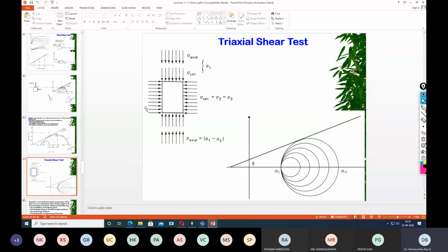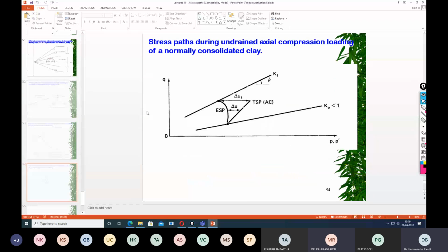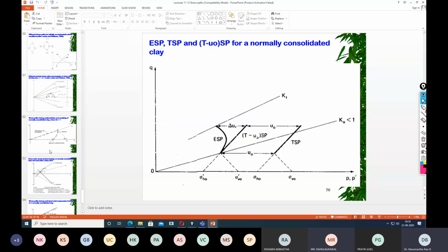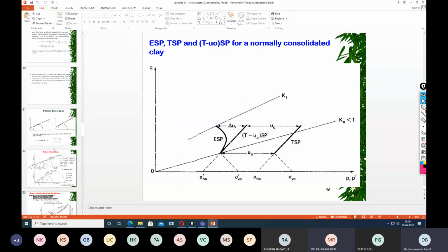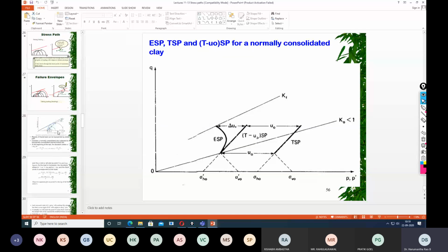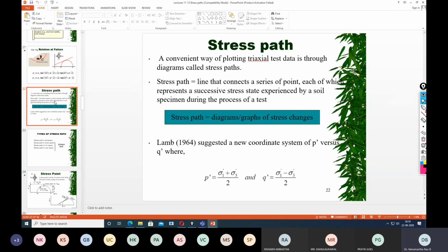Why do you think it should fail immediately? Sir, because shear strength is a function of effective stress, and effective stress is going to reduce when the groundwater table rises. And what about the consolidation that is done? The soil had already got consolidated.